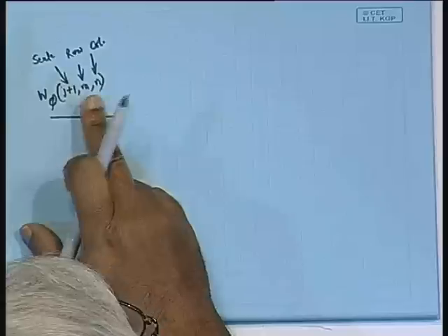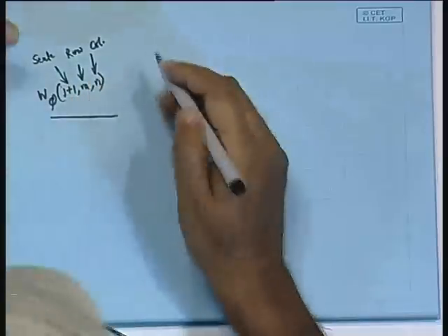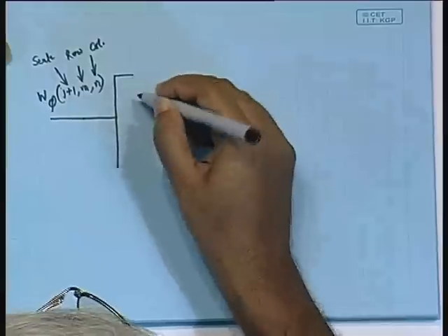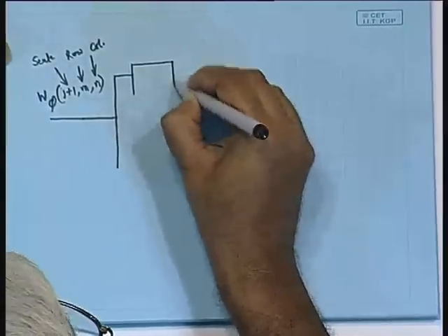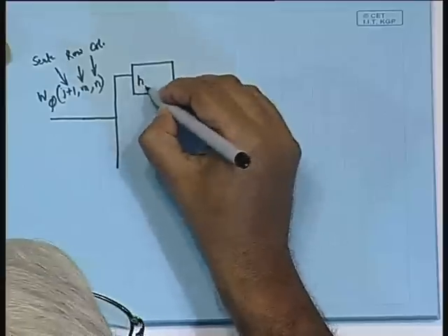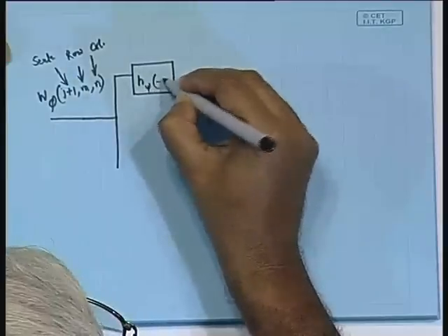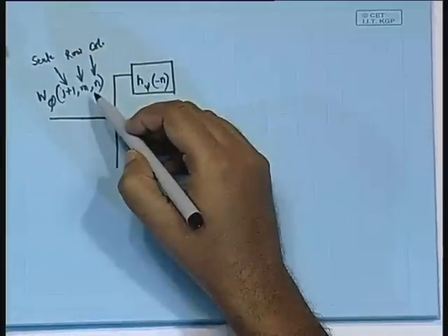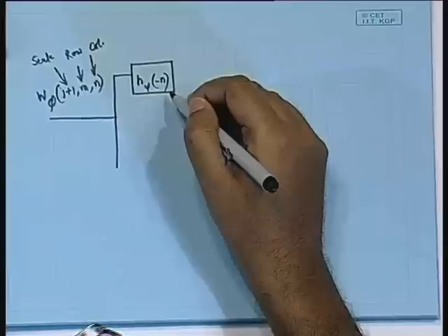First let me complete what I was trying to tell you. If W phi j plus 1 m n is the starting signal, then we pass this signal through 2 filters, and one filter is what we call H psi of minus n. Now, n is the index of the column, so this is the filter that we apply along the columns.